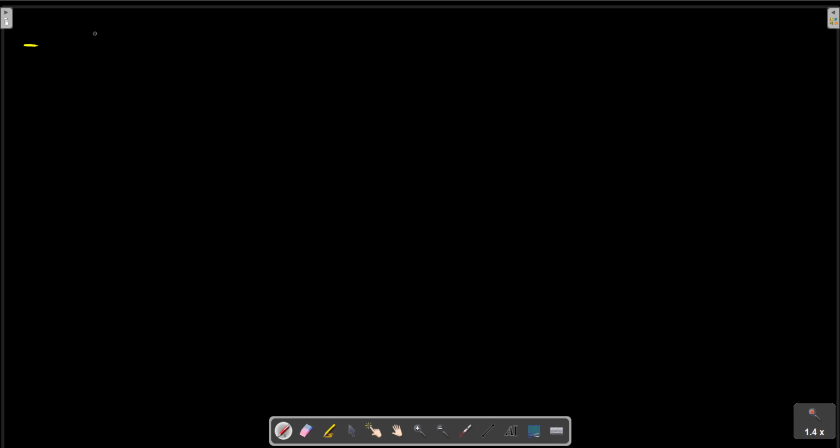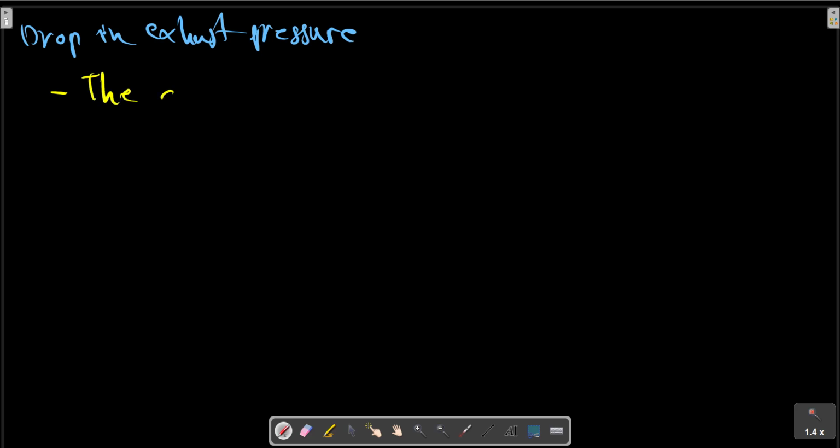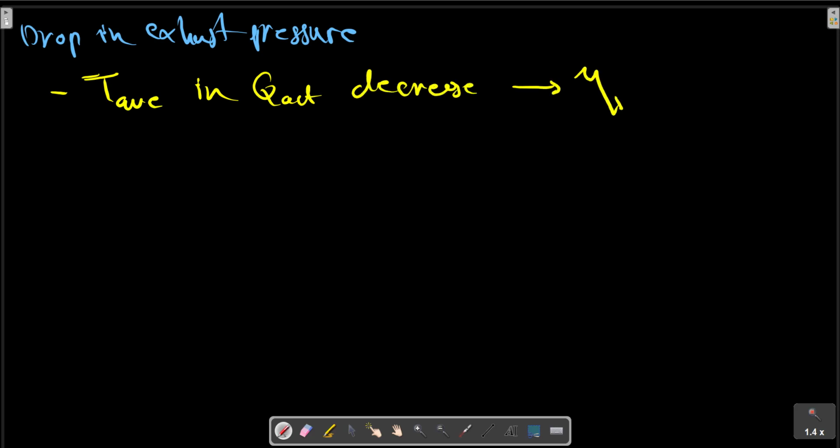This is also evident from the fact that the average temperature at which heat is rejected is decreased. Note, however, that lowering the back pressure causes the moisture content of the steam leaving the turbine to increase. This is a significant factor because if the moisture in the low pressure stage of the turbine exceeds about 10%, not only is there a decrease in turbine efficiency, but erosion of the turbine blade may also be a very serious problem.